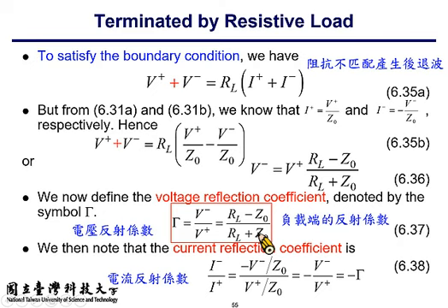On the other hand, if your transmission line is terminated with an inductor or a capacitor, or a combination of reactive components and resistive components, then your reflection coefficient is a complex number. But so far, we are dealing with the simple cases. Providing that the termination is resistive, the reflection coefficient is a real number between 1 and -1.